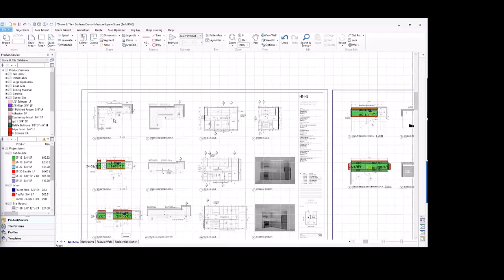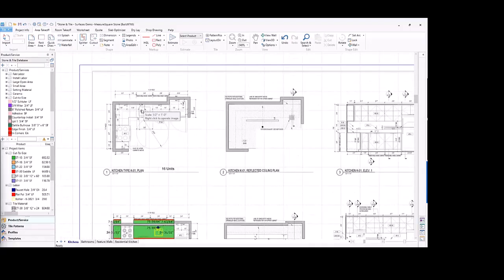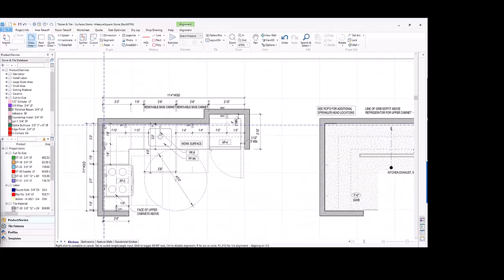So now I'm going to move on to just doing a basic takeoff of this countertop here. To do this takeoff, I'll have to use a drawing tool. Up here in the toolbar, under the area takeoff module, there's a tool called the Draw Area tool. I'll go ahead and left click on that, and you'll see a crosshair pop up. I'm simply going to left click on this corner here because that's where I want to start. Let me zoom in real quick to make it more accurate. And then I'll left click and move my mouse over to the next corner, left click again.